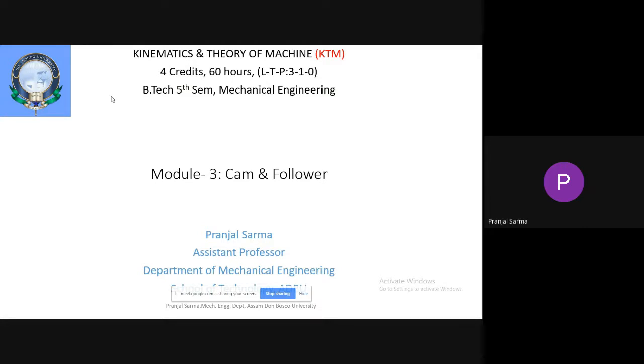This is for a planar mechanism, and it is basically valid for lower pair mechanisms. P1 is for lower pairs, and if there are higher pairs, then P2 will also be there. So you should be able to draw the configuration diagram, then find out and show the different links. P1 and P2 are also required. For finding out P1 and P2, basically you can go for the method of inspection, or there are other methods available like the loop closure equation. But at your level, for most cases you'll be able to find out P1 and P2